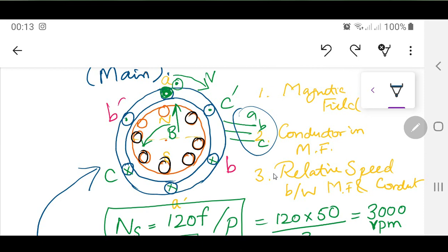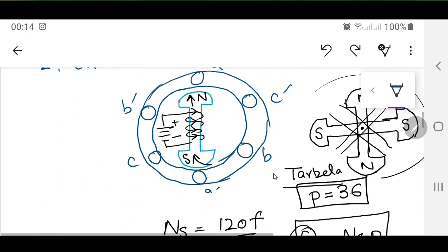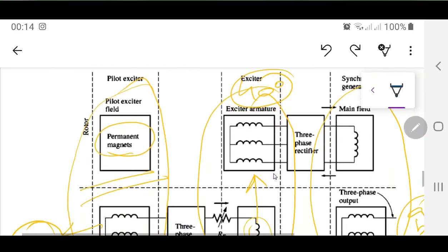Now why I'm using the word distorted, because if you remember, in a DC machine the magnetic field was in one direction, produced because of static poles, so it was a constant magnetic field; it was not changing, it was not moving. Here the magnetic field is moving, and it is moving with the speed omega. So the problem here is that when it is moving with the speed omega, and a stator magnetic field is also being produced, it's going to change its phasor orientation. Again, this is the phasor orientation because I am talking about an AC generator at present.